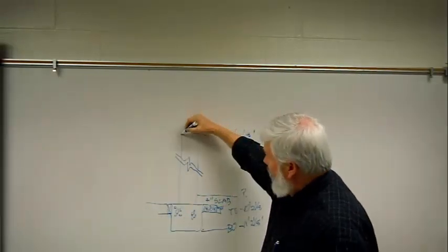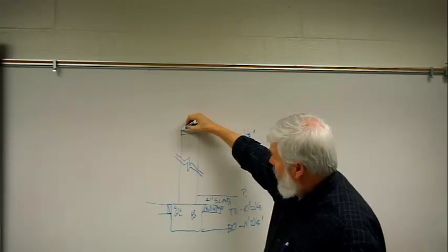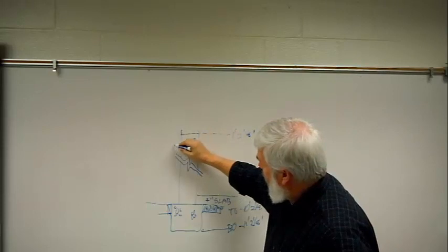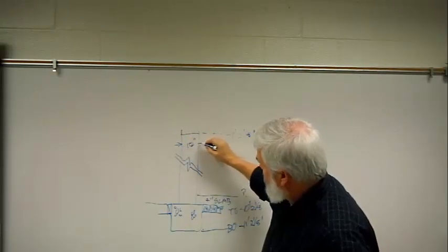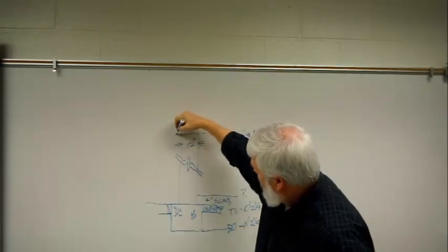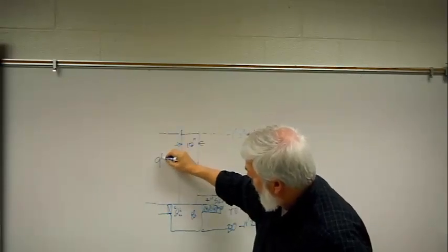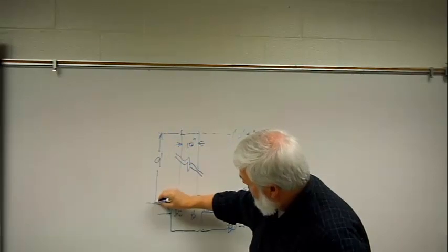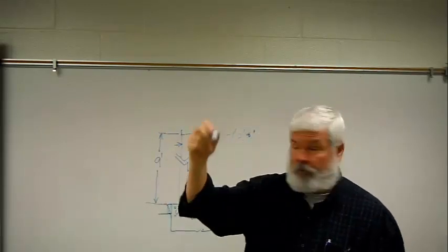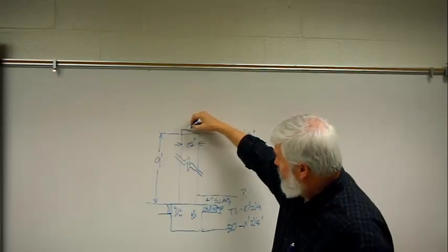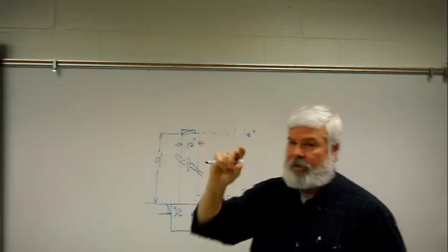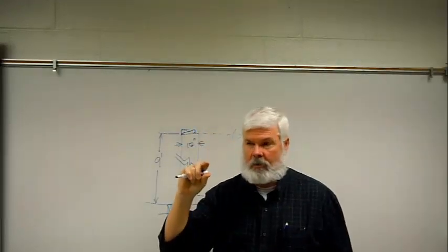The typical sill plate, if we're doing a 10-inch-wide concrete wall, which is pretty common when you're doing a 9-foot high wall, I'm going to go ahead and show that dimension here. 9 foot high is the actual concrete wall. The forms that are used are 9 foot tall. We usually put a 2x6 plate up there. So what is the thickness of that 2x6?